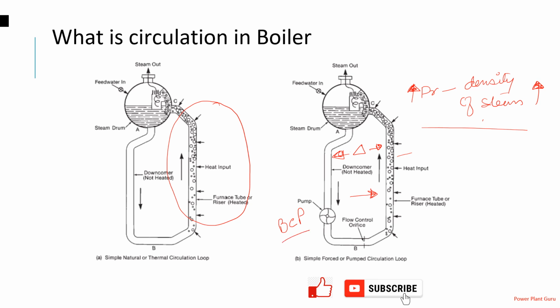In higher capacity boilers, you will see a BCP, boiler circulation pump, which is there to maintain this circulation, so that whatever heat is provided in this area, sufficient water circulates to take that entire heat and get out as generated saturated steam. So this is one important concept where the density difference comes into play.